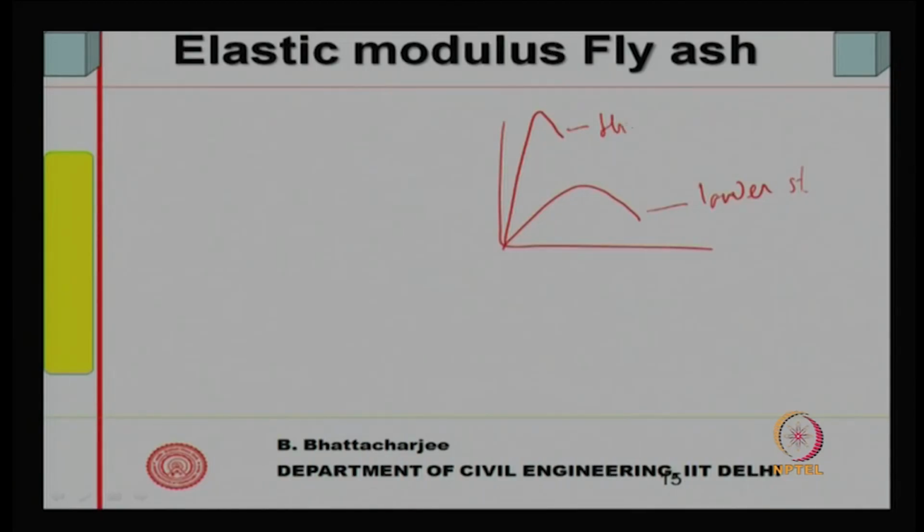So, for higher strength concrete, you can see the modulus of elasticity increases, and the deformation at which it fails is also relatively less. Actually, this behavior is between the cement paste behavior and aggregate behavior, since you improve the cement paste somewhat. Therefore, this behavior is realized in case of high strength concrete, so you have higher modulus of elasticity in high strength concrete.